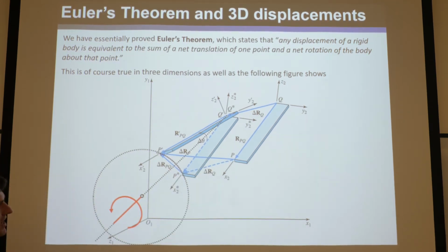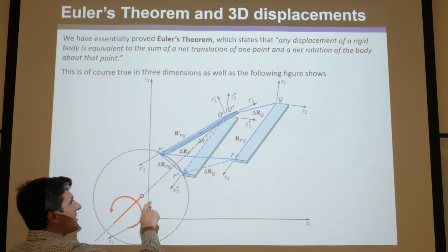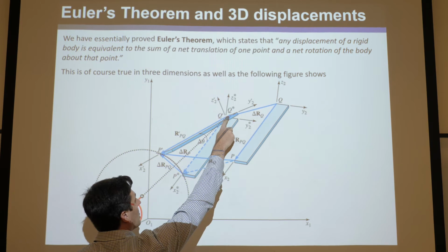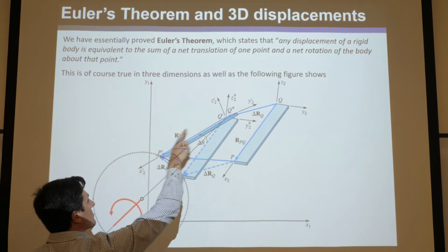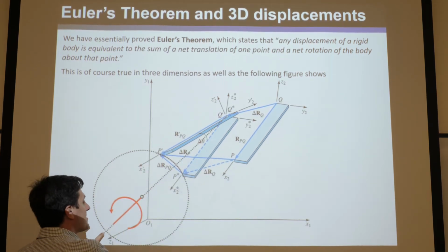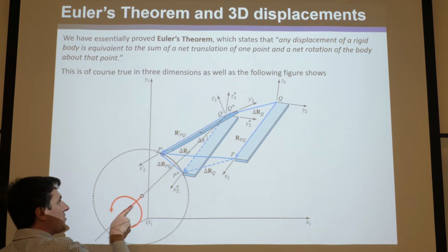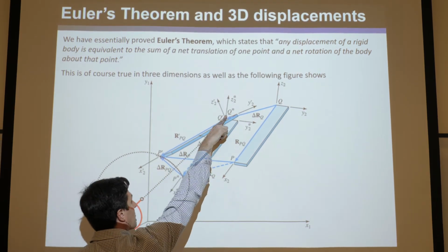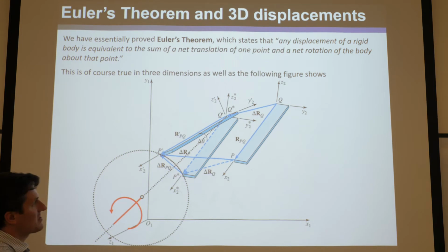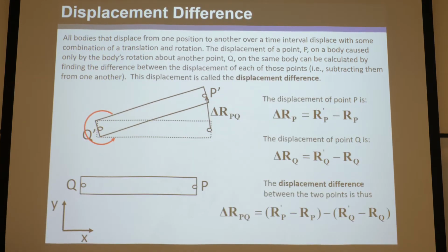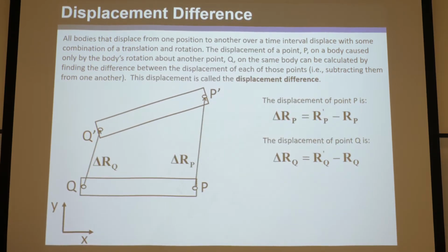But again, the path doesn't matter, it's the displacement of P caused by the rotation about Q. If you can see, it's kind of like a cone, where the tip of the cone is right at Q, and then it opens up like an ice cream cone into this big circle, and the center of the cone is the axis it's rotating through, going through Q.